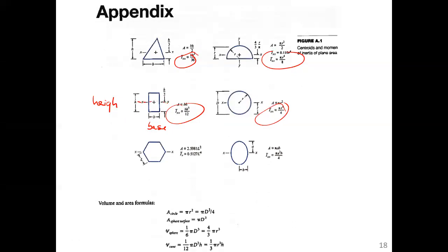So in this case, the moment of inertia, I_xx, the moment of inertia about the centroid, that's I_C, or I_G, is equal to 1/12 B H cubed. There may be a problem where you want the moment of inertia about the axis perpendicular to that, okay? So you need to be painfully aware of when you're using this, what it applies to in the variables.